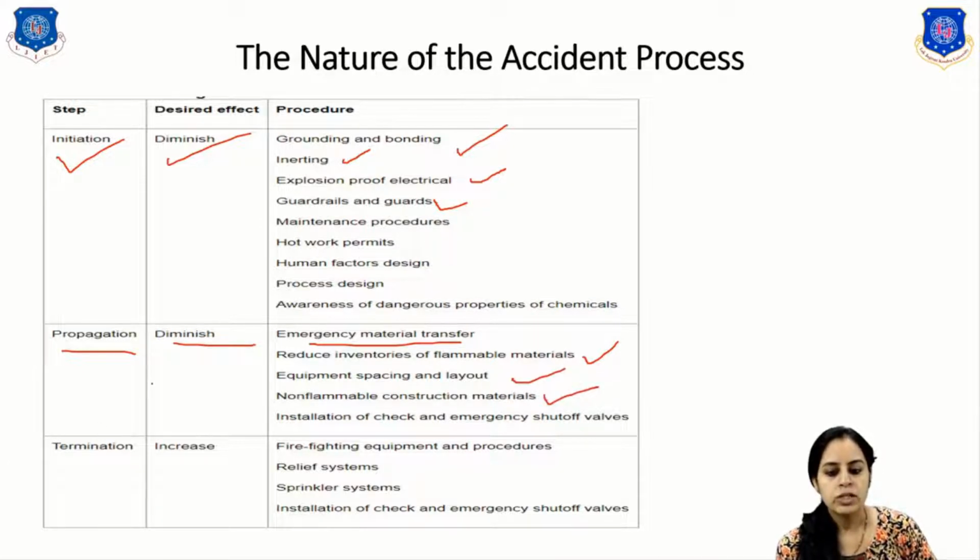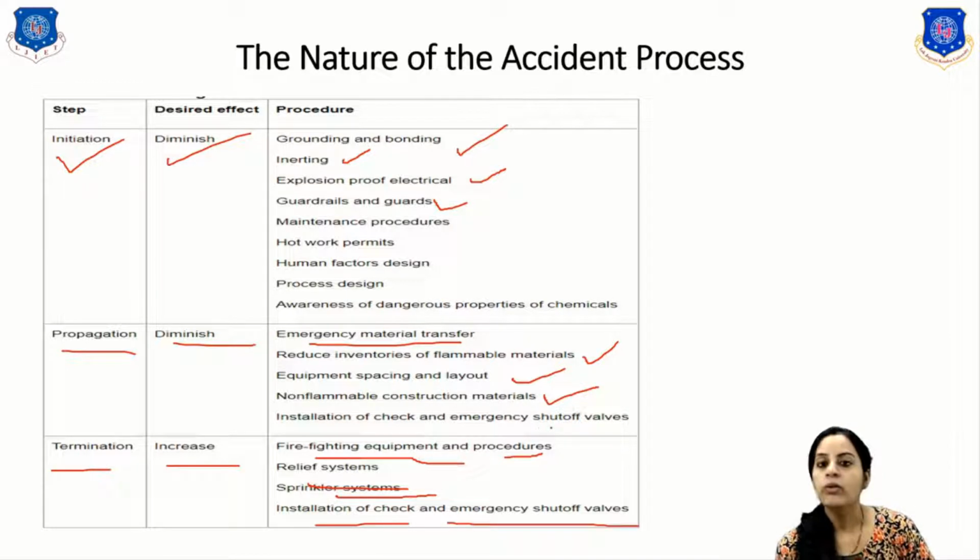And the last, termination, where the desired effect is to increase: firefighting equipment and procedures, relief system, sprinkler system, and installation of check and emergency shutoff valves.